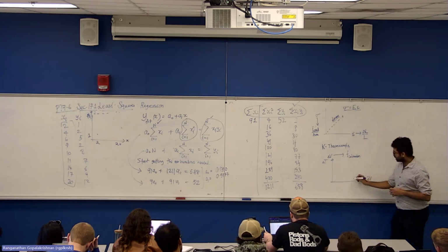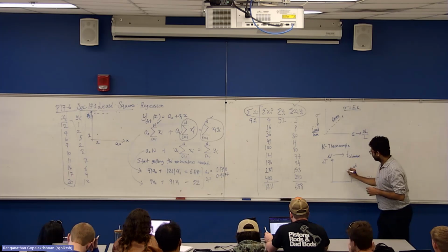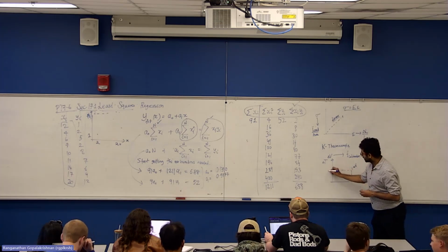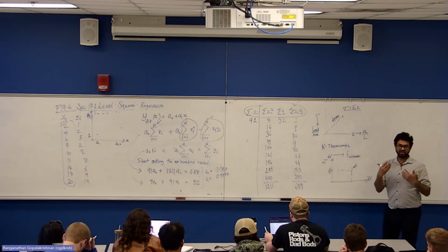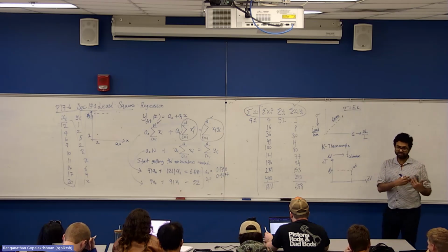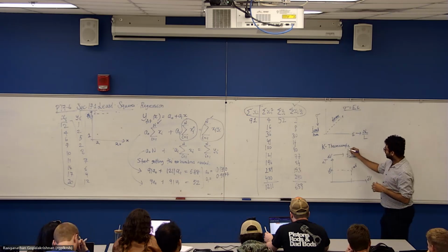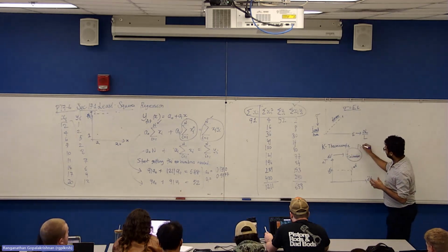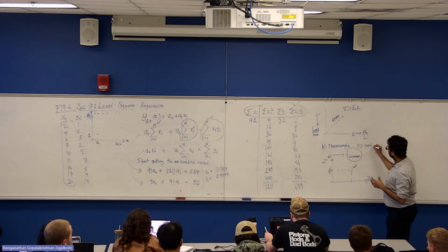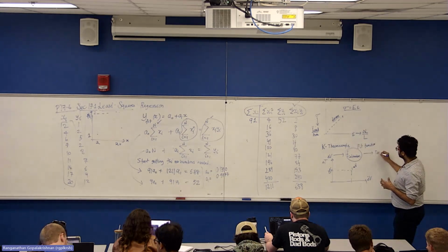So if you measured, let's say, a voltage difference of 1 millivolt, it will tell you the temperature difference is, let's say, 10 degrees Celsius. And this 10 degrees Celsius is with respect to ice point or something like a reference temperature. So then the instrument is already programmed in with the calibration relation, which is nothing but a fit function. It could be a more complicated fit than linear, and that gets you a temperature.